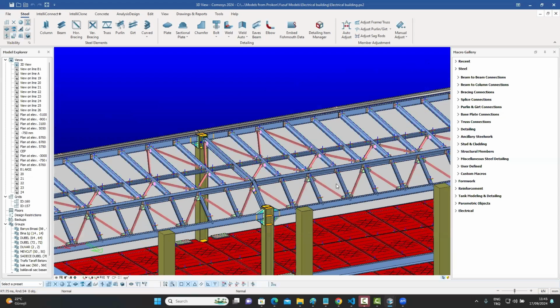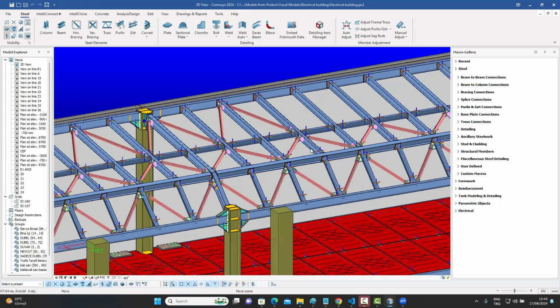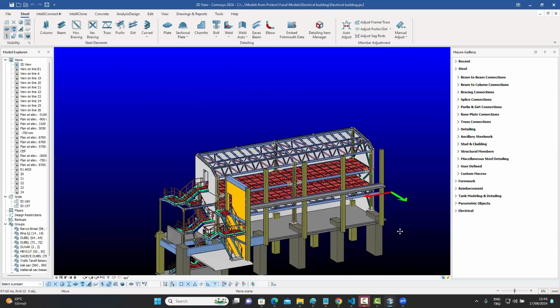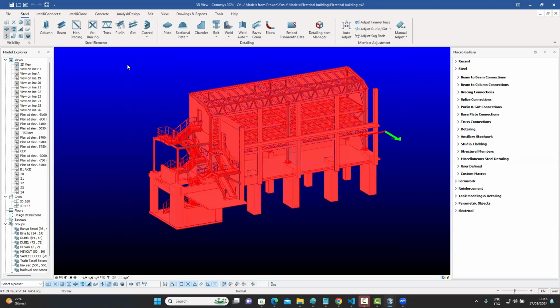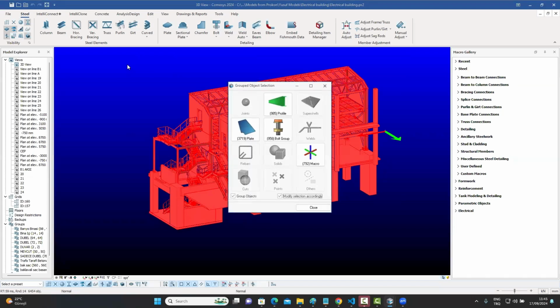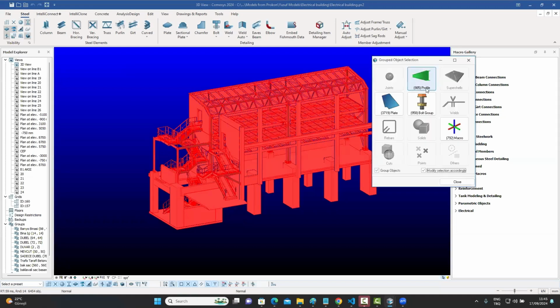The main profile of the macro should be HEB 300, and that's what I want. So what do I do? If I once again use on-the-fly filtering and just select everything like that and press enter, now you see, I've discussed this dialog box that we can see the 985 profiles, 3,719 plates, bolts, etc.